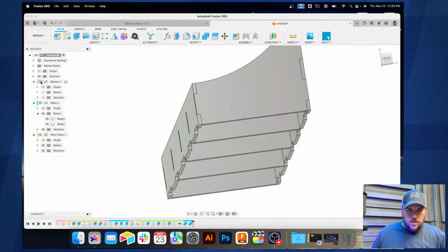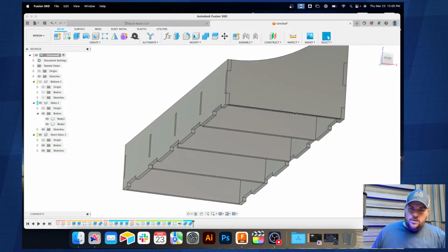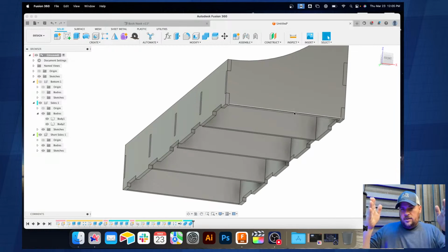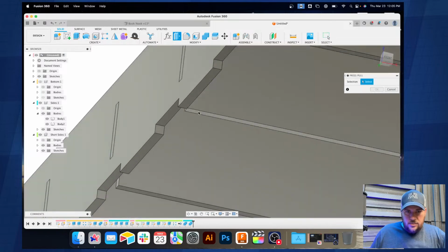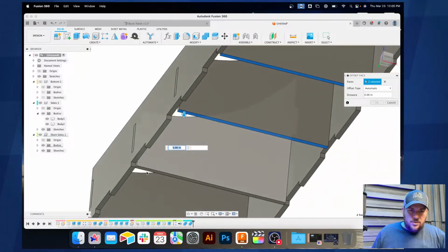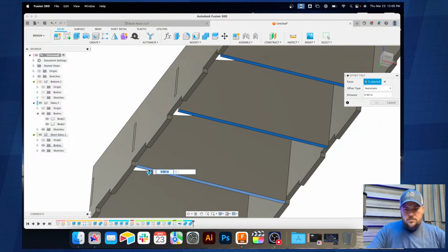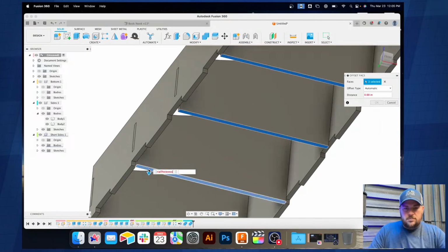So if I get rid of the bottom, the problem is I wanted the two on the outside to overlap because they're going to interact with the tenons. The ones in the middle are not. So I can very easily just go change those. You can go back and make some exceptions to the rule, but I can also do this. Minus material thickness. There you go.